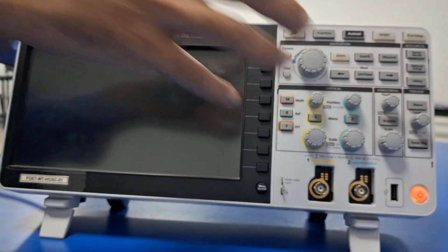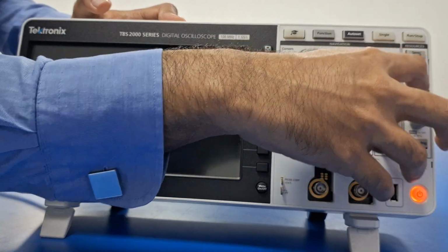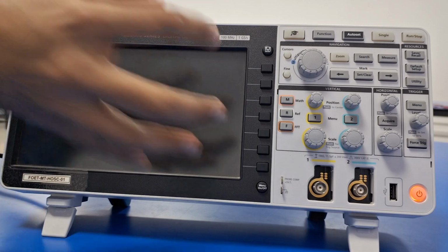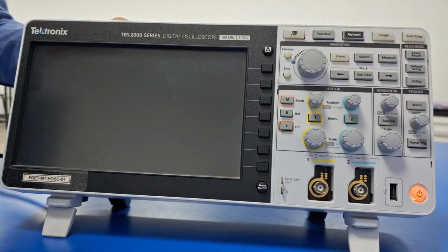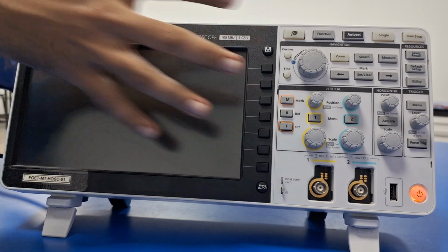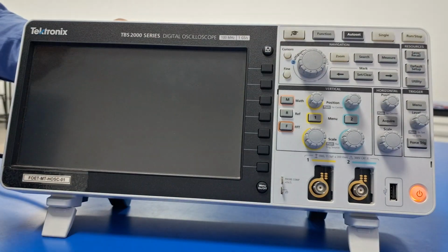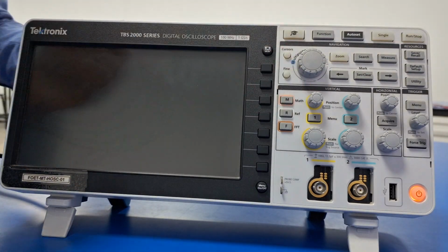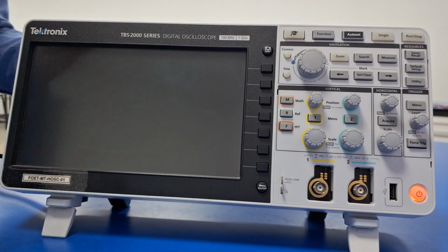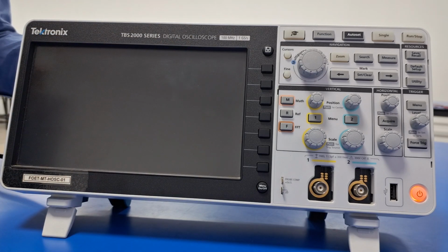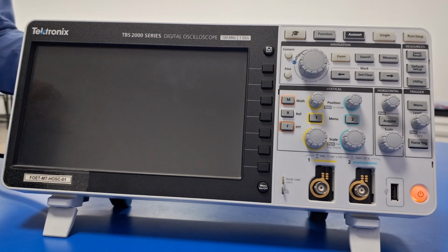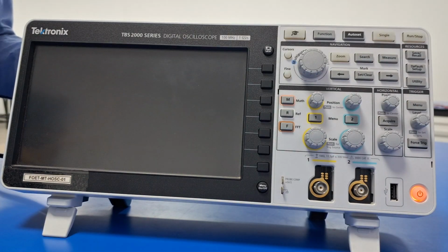Then we have the most important system, the trigger system. This is usually not touched much in a digital oscilloscope in the initial stages, but it is what makes the waveforms still and readable in the oscilloscope. The trigger function basically aligns a trigger so that your waveform is displayed still on the display. There are different types of triggers. You can have an edge trigger, and edge triggers can be divided into rising edge triggers and falling edge triggers, and many more other functions. Let's look at that in later videos.